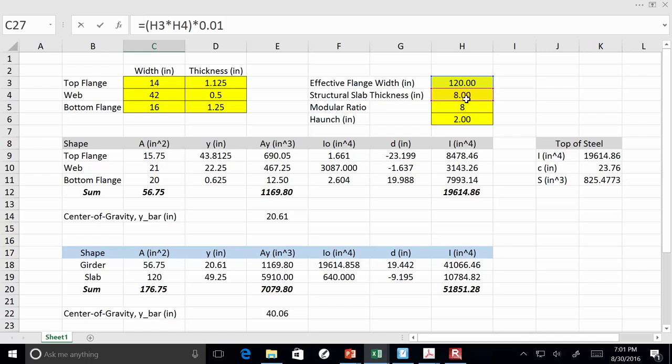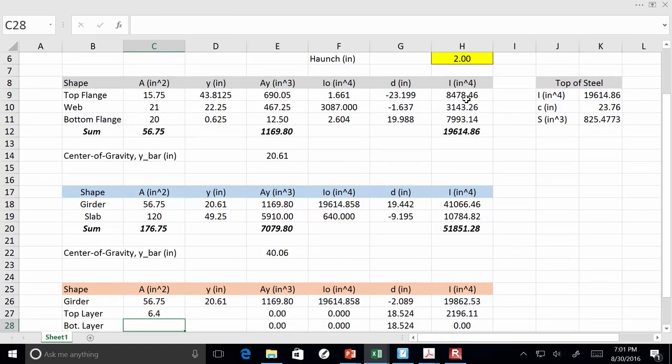And then on top of that, we say, okay, we got all this rebar. How much went on the top? We had some amount go on the top, some amount go on the bottom. Anybody remember? 2/3 went on the top, 1/3 went on the bottom. So put 2/3 on the top, and there you go.